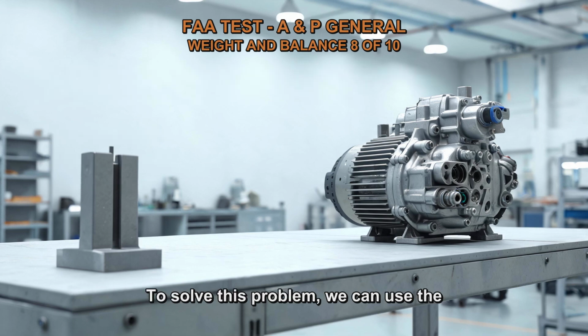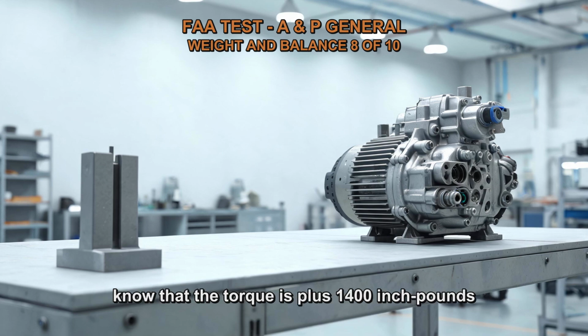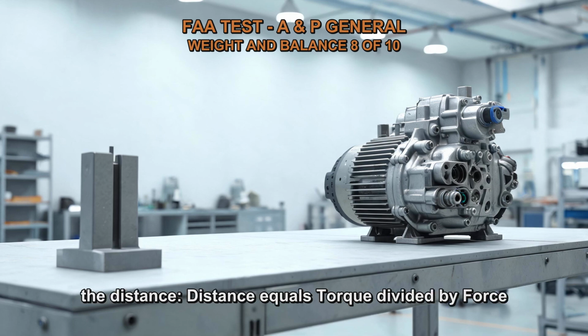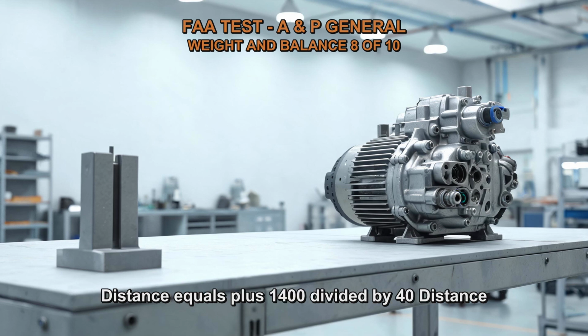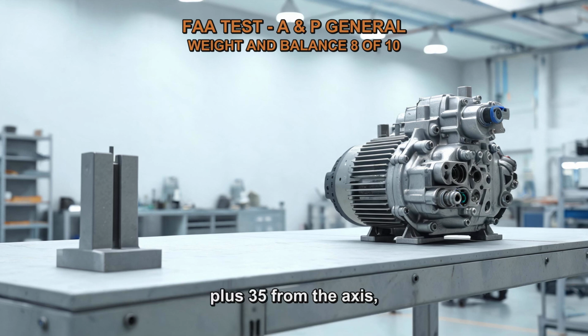To solve this problem, we can use the formula: torque equals force multiplied by distance. We know that the torque is plus 1,400 inch-pounds, and the force is 40 pounds. We can rearrange the formula to solve for the distance. Distance equals torque divided by force. Distance equals plus 1,400 divided by 40. Distance equals plus 35. Therefore, the generator is located plus 35 from the axis.